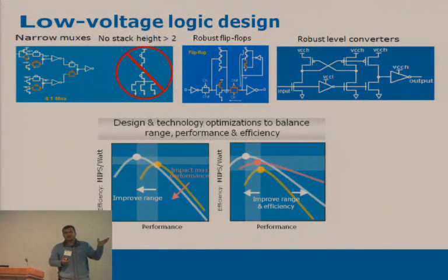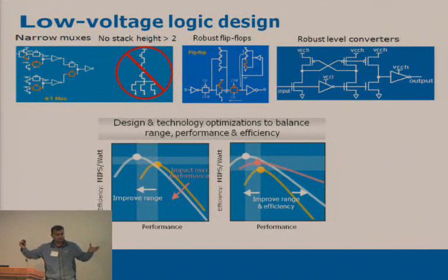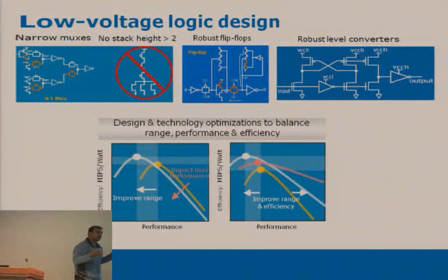A lot of these choices you make, as I talked about, for example dynamic platform control: you shut down things when they're not active. That improves your active energy budget of the remaining components, so that helps your operating range. But some of the choices, like bigger SRAM cells or low fan-in gates, do compromise to some extent the Fmax side of things, right? Because you have a lower power budget, less frequency. So you have to really balance them carefully.